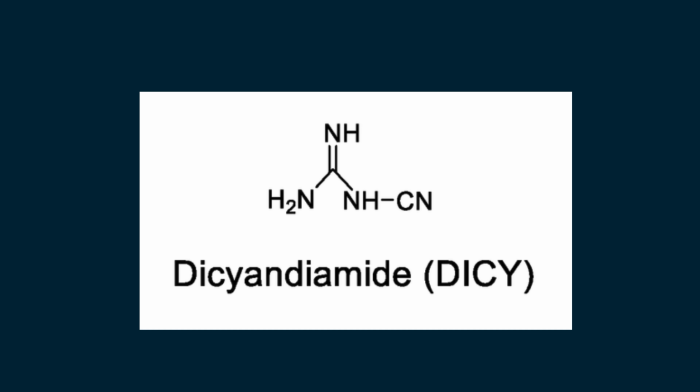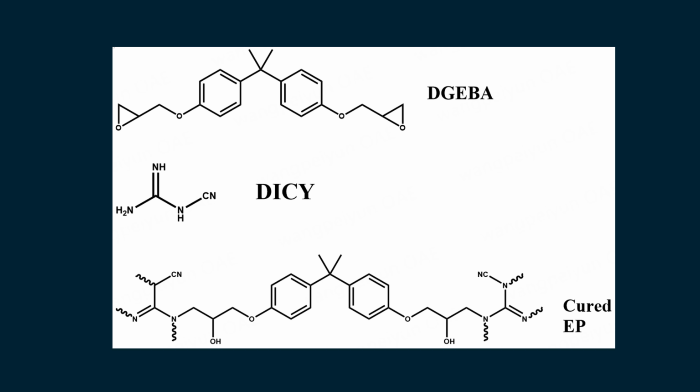Dicyandiamide, DICY. Dicyandiamide is a solid latent curing agent widely used in one-component epoxy adhesives and film adhesives. It reacts with epoxy groups only at elevated temperatures, typically above 140 degrees Celsius, enabling long storage stability. DICY is typically used at 5 to 7 pph for liquid epoxies and 3 to 4 pph for solid resins.